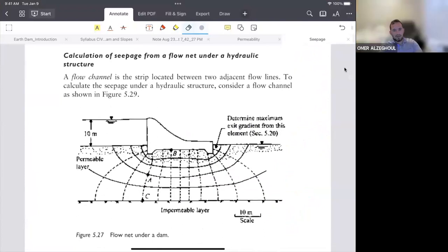Okay, and then just keep it at each point, or do we do the resultant? Each point. Okay. The result: first of all, we need to calculate at each point. After we calculate at each point, we will find the load diagram, and then calculate the total uplift force. After we know the total uplift force, we also need to calculate the total weight of the dam. And then from there, we need to calculate the factor of safety against uplift force.